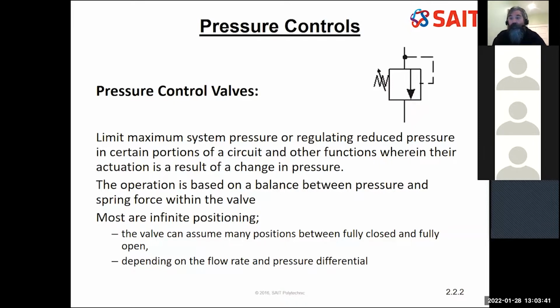So I want to clamp something, and then I may want to press onto that item. The example I'm going to give is survey stakes. In Canada, when you do a survey stake for a pipeline, there's got to be certain information on it, and it's got to be found and readable. So often what we do here in Alberta with gas pipelines is a piece of metal comes through a press, and then it will be clamped down in place, and then we'll have a machine that punches the information into it or presses the information into the metal.